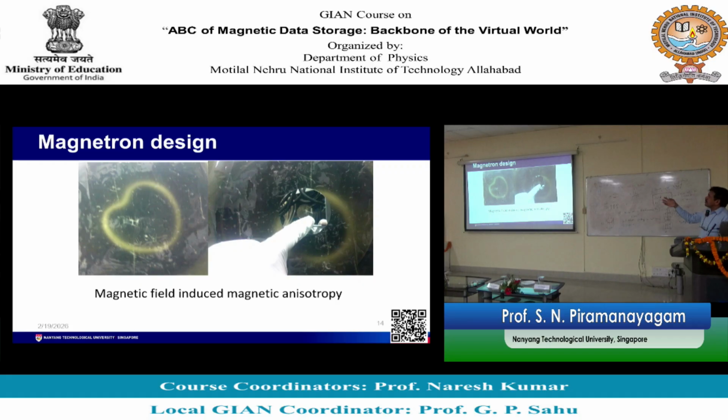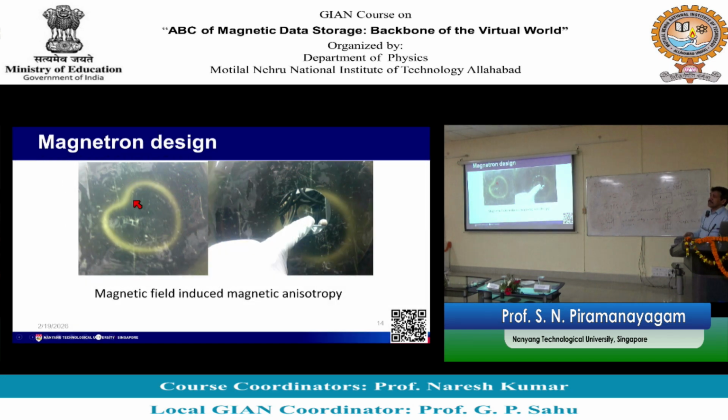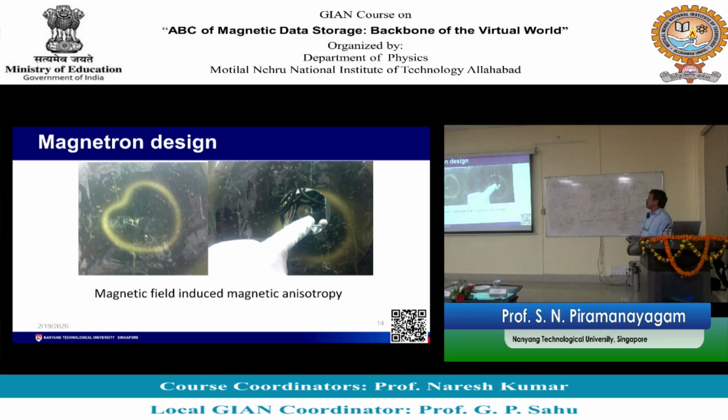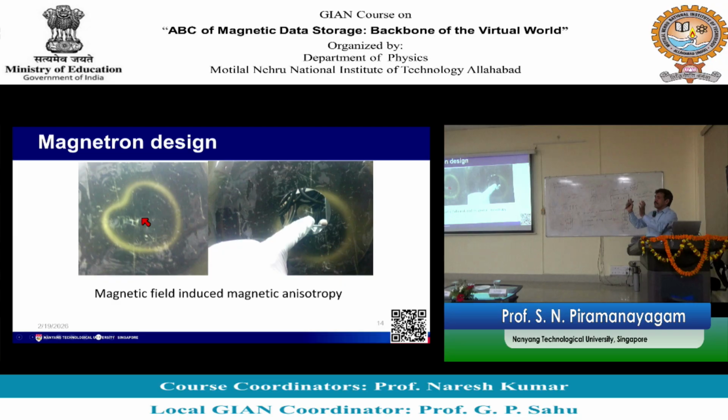This picture is like we open the chamber and we place a sheet above the magnetron, then we can visualize. You can buy this kind of sheet on Amazon. It's a magnetic visualization sheet. If there is a magnetic field, you put this sheet and you can visualize it. So, the field lines are like this. This is based on the heart-shaped magnet array which I showed you on day 1.